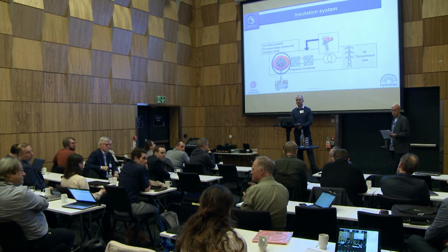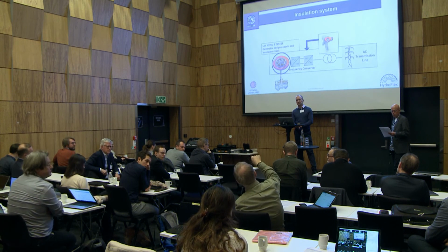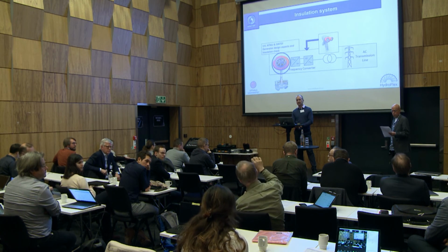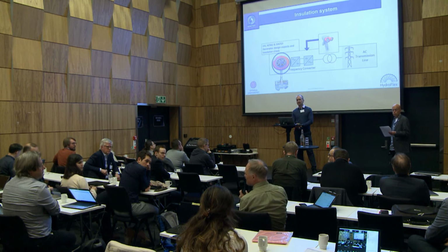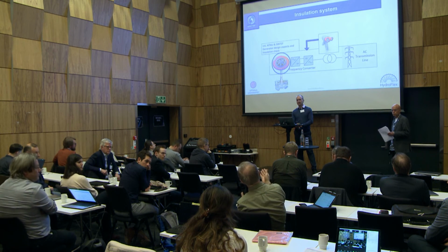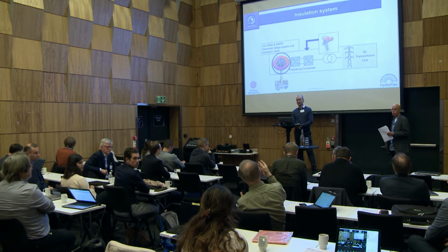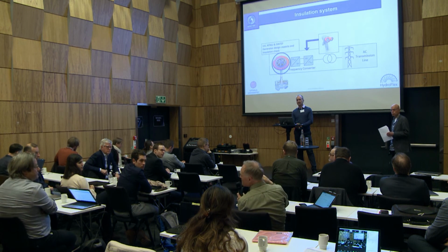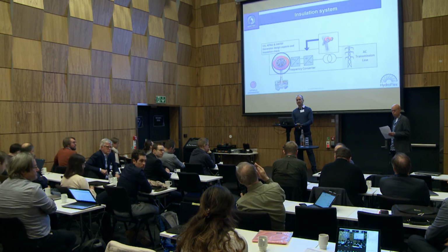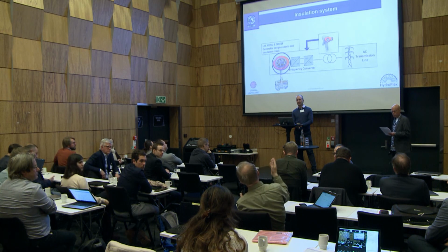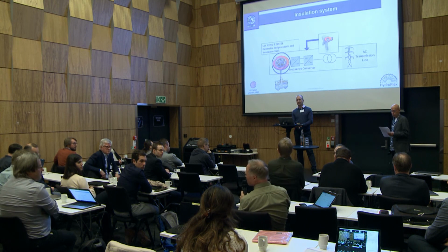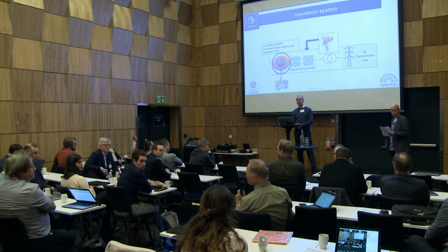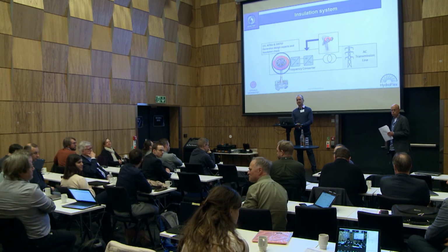Just a comment on this frequency. If you only have a converter between the grid and your generator, you do not need to design it for 50 hertz. You could choose everything. I had a PhD student investigating this, and there's not so much to gain then. It's a little bit, but then your machine may be unstable in the power system if you really want to put it directly. We also did this in ABB some years ago for Three Gorges. But the result from my PhD student was that something between 42 to 48 hertz is very good. So I think our predecessors were quite smart selecting 50 hertz. It's quite a good choice.